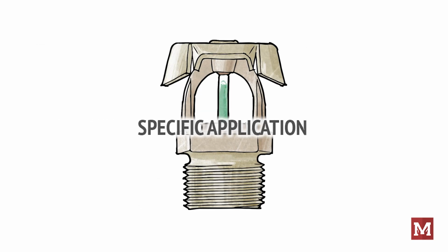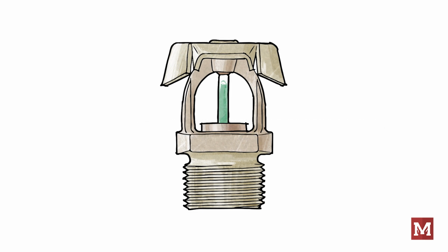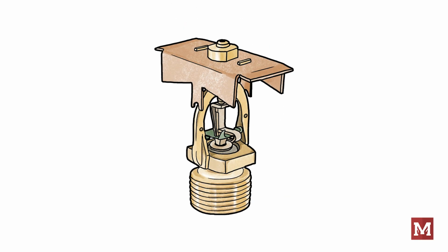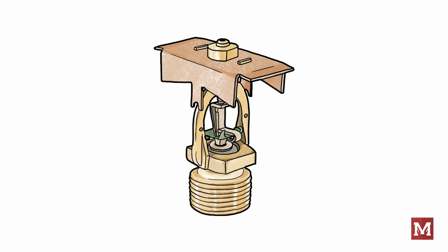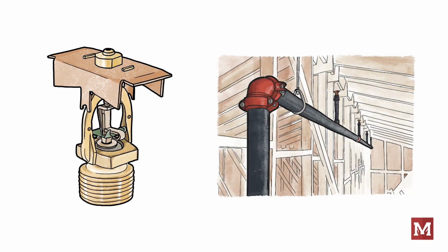What are specific application sprinklers? Specific application sprinklers have been developed to meet some challenges that's been faced in the construction industry. I'd like to talk about attic sprinklers first. The story goes some sprinkler deflectors got smashed on the way to the testing lab, and someone said, hey, let's look at them anyways. Put them into the testing apparatus and found that the spray pattern looked like it could work under a steeply pitched roof.